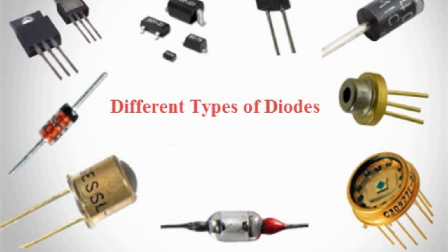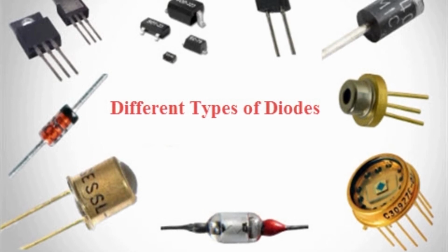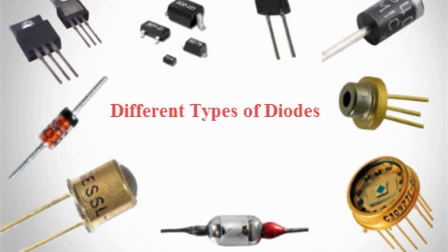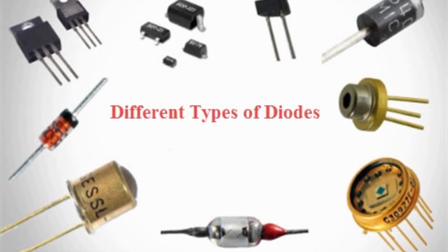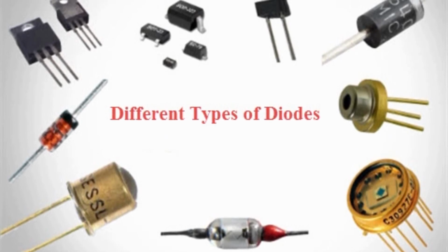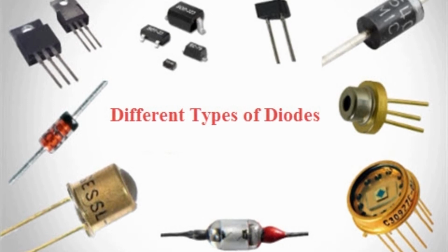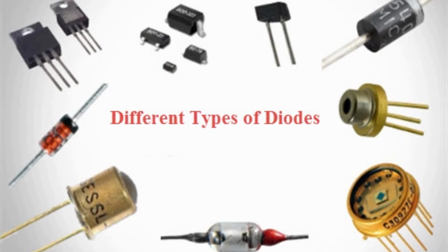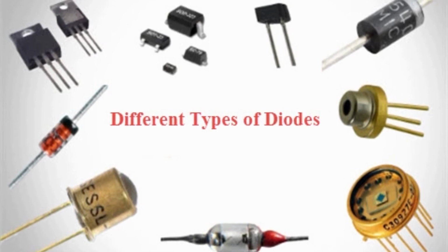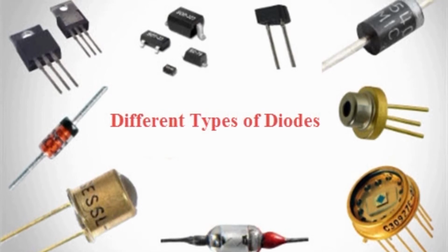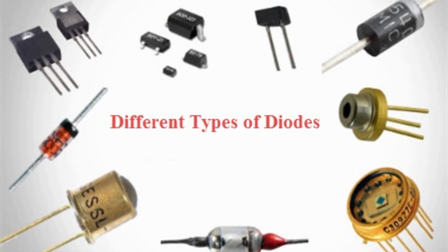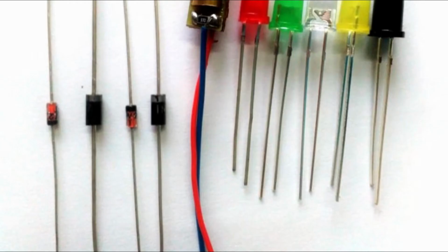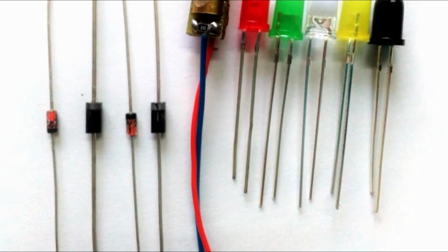Silicon controlled rectifier: As the name implies, this diode can be controlled or triggered to the on condition due to the application of a small voltage. They belong to the family of thyristors and are used in various fields of DC motor control, generator field regulation, lighting system control and variable frequency drive. This is a 3-terminal device with anode, cathode and a third control lead or gate.